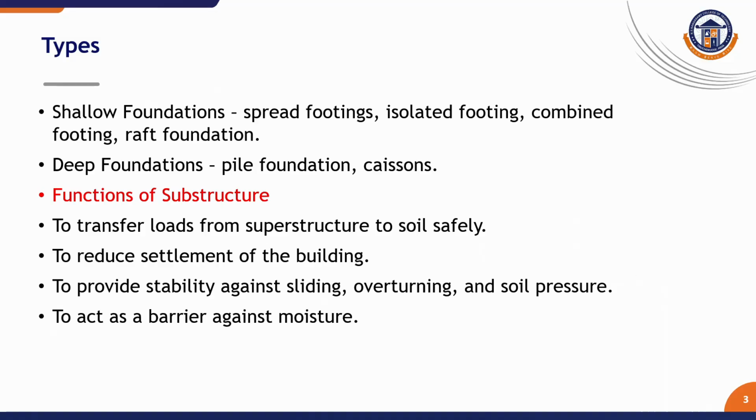The functions of substructure are to transfer the loads from superstructure to soil safely, to reduce settlement of the building, to provide stability against sliding, overturning, and soil pressure, to act as a barrier against moisture. The main function is to transfer the loads from superstructure to soil safely.